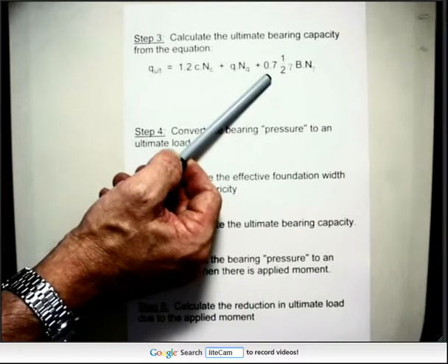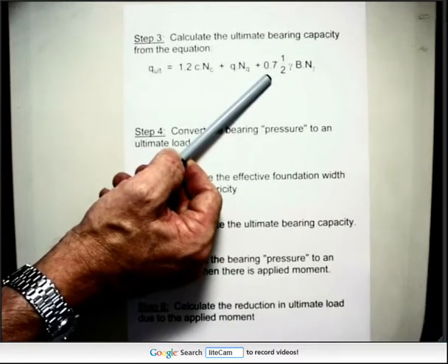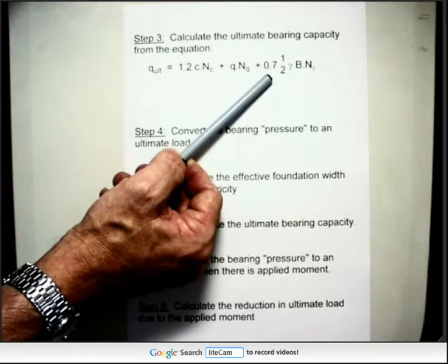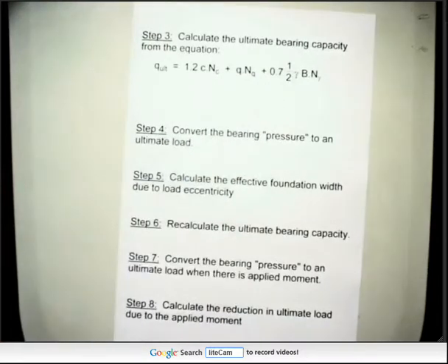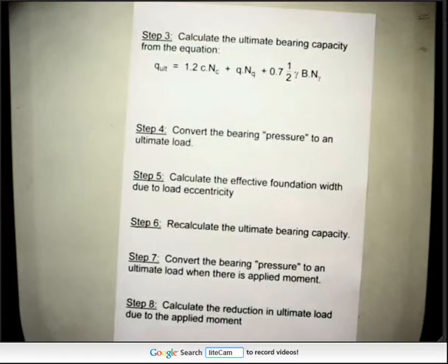I think that was the Brinch-Hansen shape factors I was using there. But if it does, just correct it now. But it gives you an idea that actually geotechnics isn't that accurate. Nobody can really say which one, whether it's 0.8 or 0.7, to any real degree of confidence.